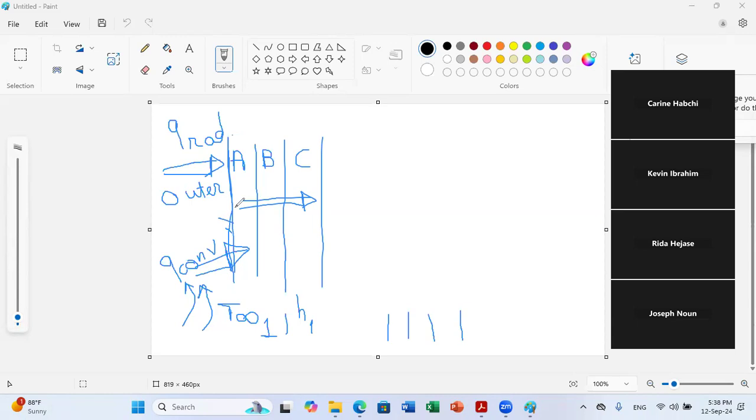And then, let's say you have 3 layers of solid, and within these layers, heat is transferred by conduction. Then heat will be transferred to the inner space, and it can be a combination of convection and radiation, or only convection, depending on the case. So depending on the scenario that is proposed, sometimes maybe they will tell you you just have convection, so radiation can be neglected compared to convection.